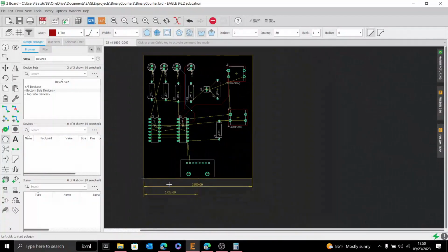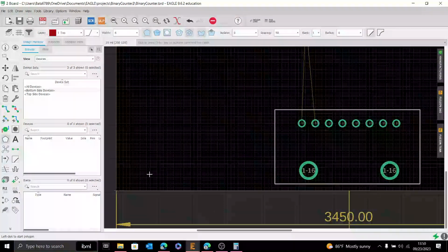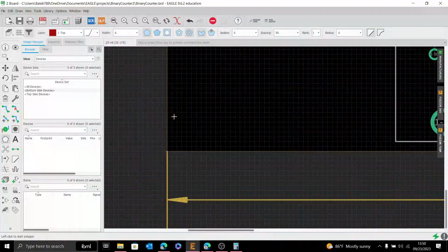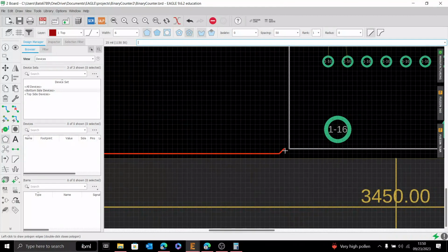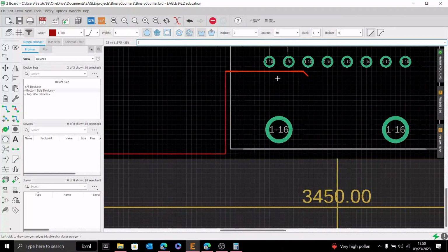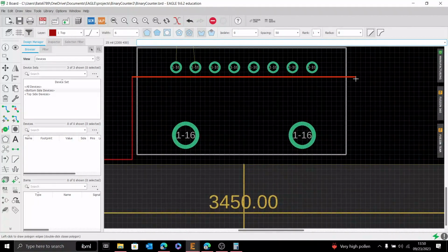And so here's what I'm going to do. I'm going to take into consideration that I will eventually want screw holes in the corners. And we're just going to place those like so. So what I'm drawing now is the outline of my ground pour. So whatever is inside this bounding box will effectively just be a sheet of copper for all the ground stuff to connect to. And you don't have to be as strict with your 90-degree rule on planes.